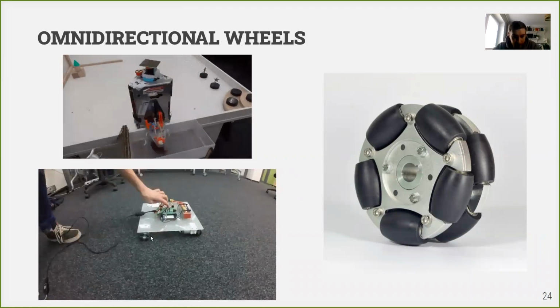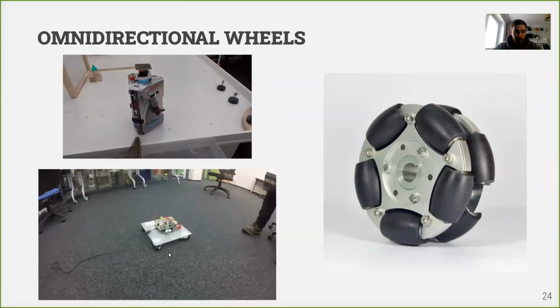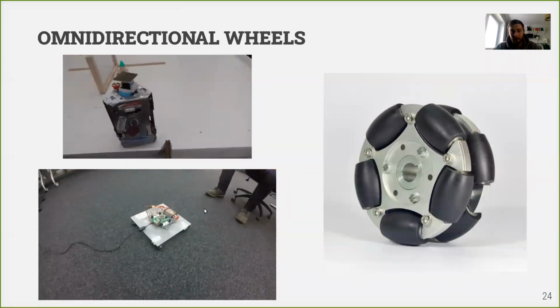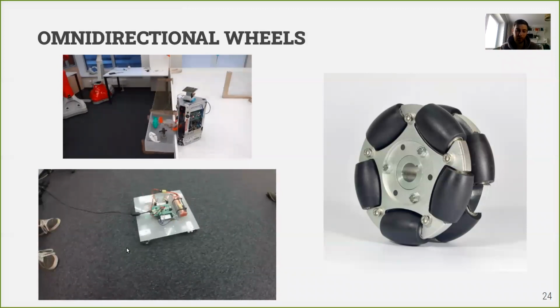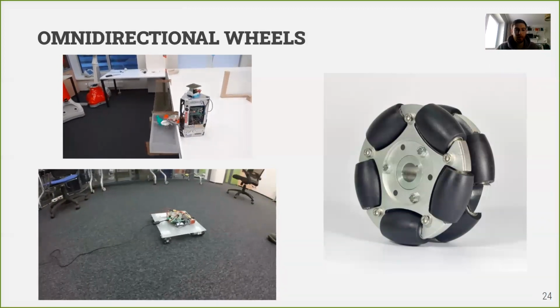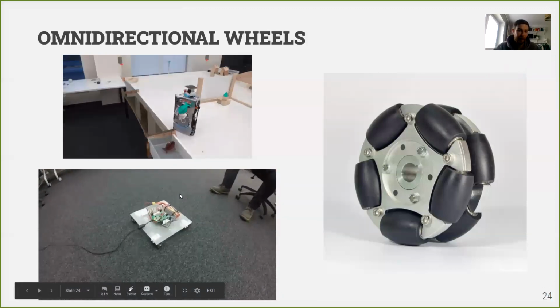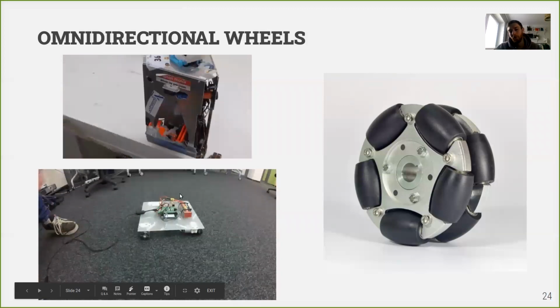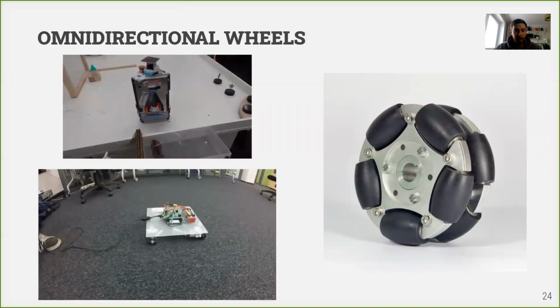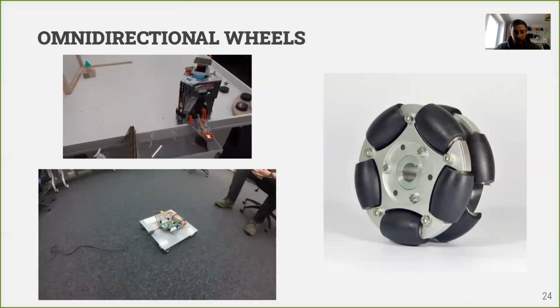But you can understand easily that we are not using all the power of our motors to move, because at any given moment of time only two motors work and two others just do not contribute to motion. That is why it is not really effective to have two of four motors working all the time, because it limits our speed and our power of motion.